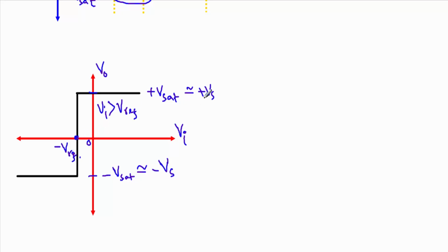So our operational amplifier will operate in positive saturation, and the points that are lying to the left, that means Vi is less than our negative reference voltage, our operational amplifier will operate in the negative saturation region. Our positive saturation voltage will be controlled by the positive power supply voltage plus Vs, and the negative saturation voltage will be controlled by the negative power supply voltage.